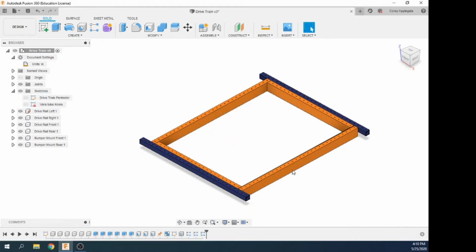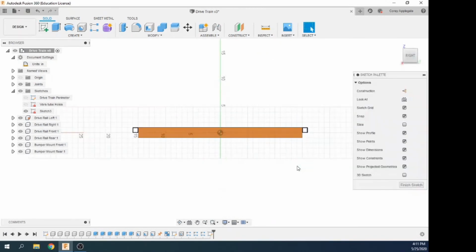So the next set of holes, as I said, we're going to drive is our gearbox and axle holes. I'm going to again stay at the top. I like to leave all my sketches that reference or drive multiple items at the top, and anything that's unique to that part, I'll sketch underneath that part. Starting a new sketch, I'm going to pick this outermost plane.